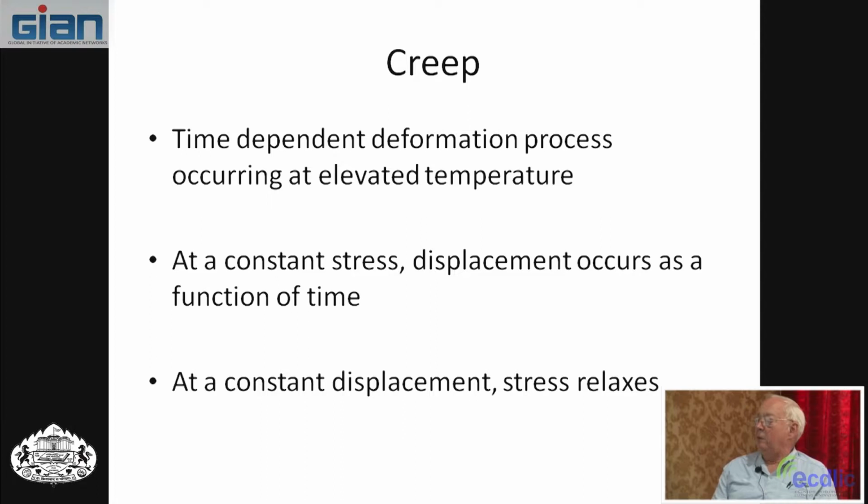At higher temperatures, the creep happens pretty quickly, maybe 1,000 hours or so. So if you have a constant displacement and you creep, then you get stress relaxation. So constant stress, you get stretching; constant displacement, hold it there, the stress relaxes.